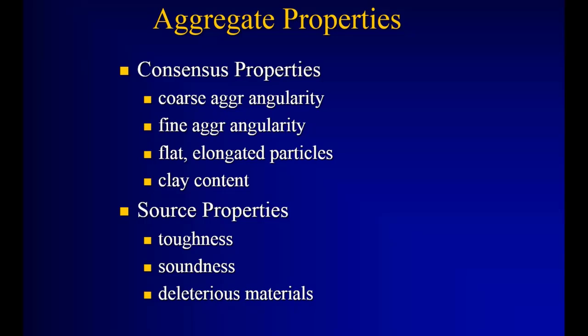And what was quickly apparent in the conversion to Superpave, particularly in North Dakota, is strength doesn't necessarily come in big rock. Strength comes from really 3 items, regardless of the size of the material. It's the angularity of it, you know, how sharp the edges are. It's the texture of the surface, the friction, if you want to call it that, and the gradation, the particle size distribution that we're using.